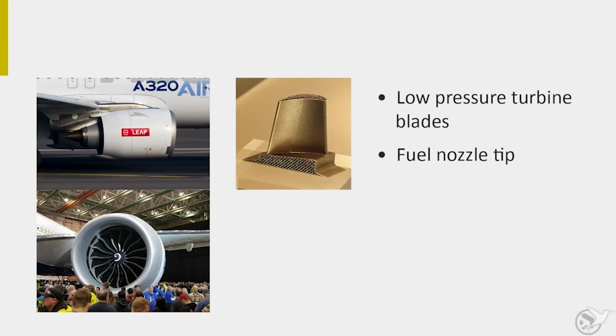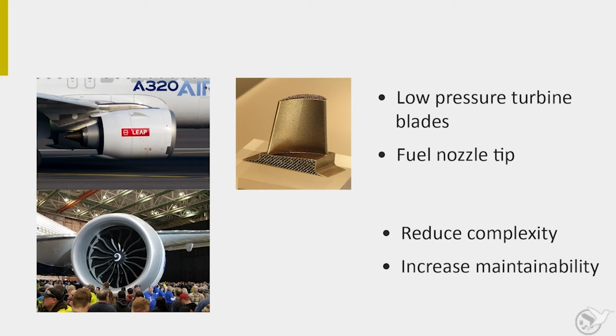So, when are we getting a 3D printed plane? Well, it might still be a little while, but that doesn't mean that additive manufacturing isn't being used in other ways in the aerospace industry today. For example, several of GE's new aircraft engines contain various 3D printed components, including the low-pressure turbine blades and fuel nozzle tip, which greatly reduces the complexity of the engine and increases maintainability.